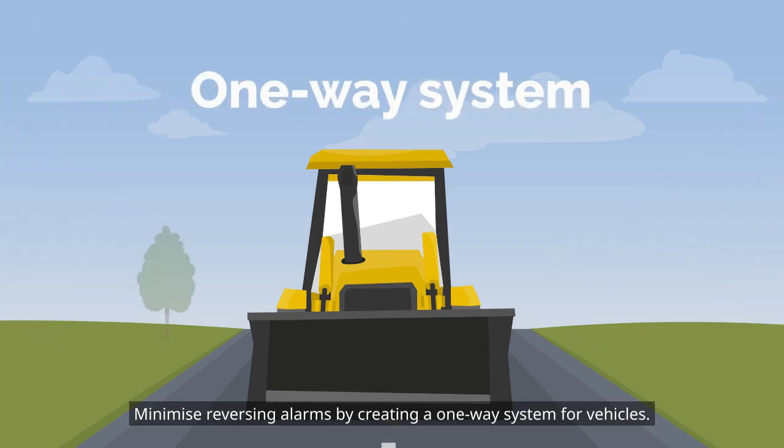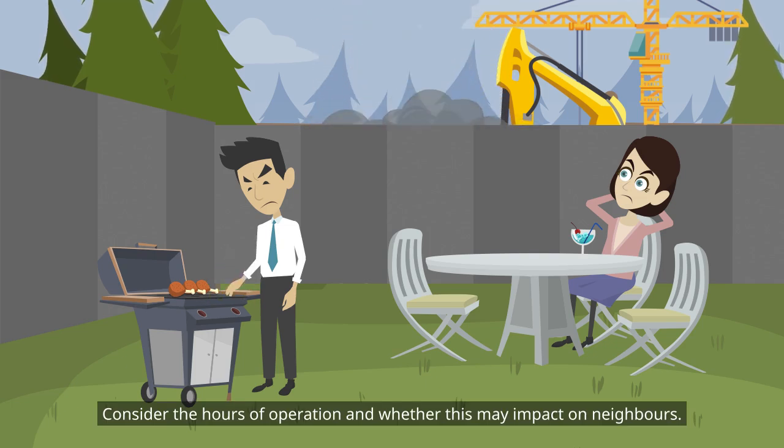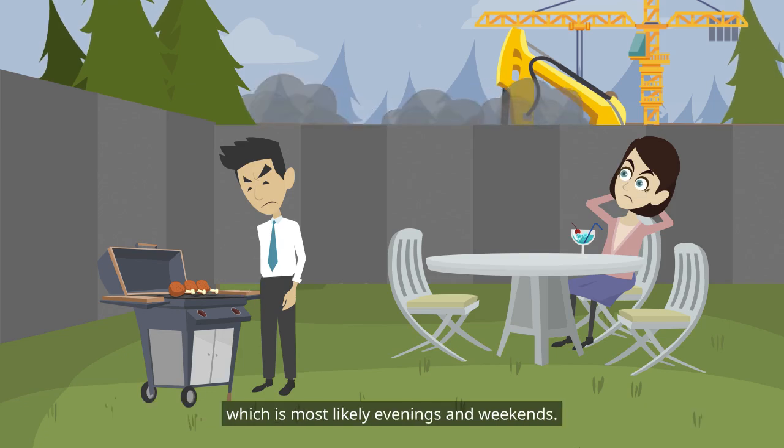Minimize reversing alarms by creating a one-way system for vehicles. Consider the hours of operation and whether this may impact on neighbors. Avoid noisy works when people are more likely to be at home or in their gardens, which is most likely evenings and weekends.